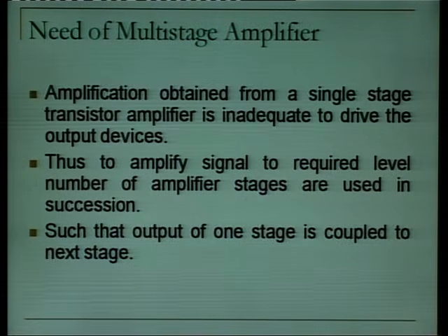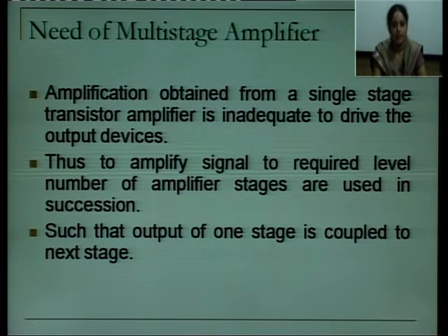Now, the first basic question that arises is, what is the need of a multi-stage amplifier? The amplification obtained from a single stage transistor amplifier is inadequate to drive the output devices. For example, your loudspeaker works as an output device. The amplification obtained from a single stage transistor is not adequate to drive the output device. Thus, to amplify the signal to the required level, a number of amplifier stages are used in succession.